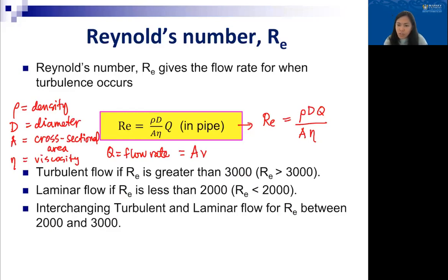Let's look at an example. Let me just see, there's a question. Can a syringe question use Bernoulli's equation if it's not a viscous fluid? The answer is yes. Bernoulli's equation can be used for viscous and non-viscous fluids. But Poiseuille's equation, you can only use for viscous fluids. You cannot apply Poiseuille's equation for non-viscous fluids.